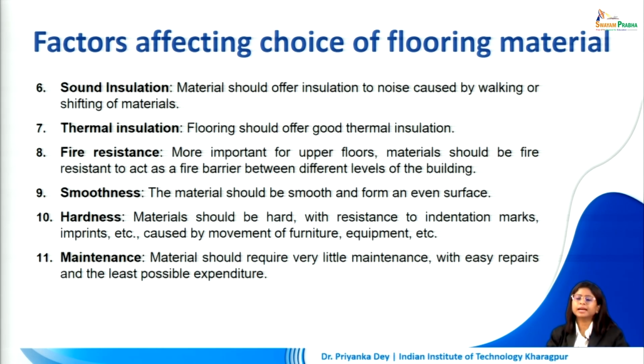However, having said that, it is also not advisable to go for very smooth surfaces as flooring in case of wet areas. So we don't want very slippery material to be used in washrooms or areas where we can expect rainwater or any other form of water to fall on the floor. In that case, we might want to restrict the amount of smoothness our flooring material has. So it depends, of course, on the usage of the room that we are selecting the flooring for.